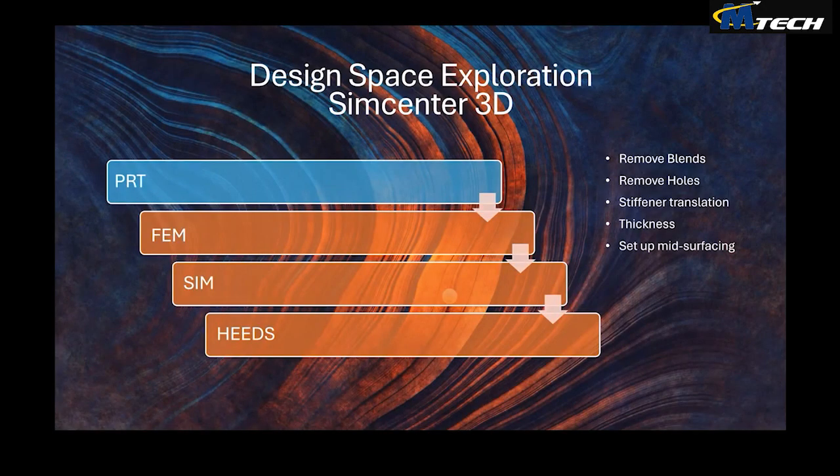In this video, we're going to work on a part file. We'll walk through removing the blends and any unnecessary holes. We'll create a mid-surface mesh, and we'll set up the thickness changes for the web, as well as position changes for the stiffeners in the FEM file.